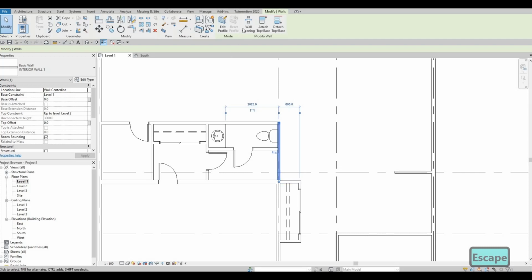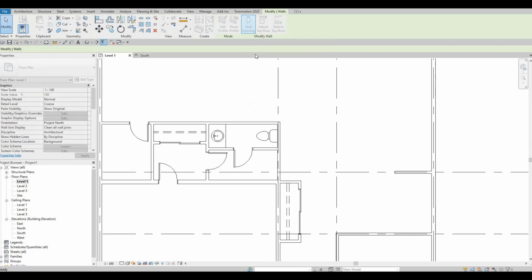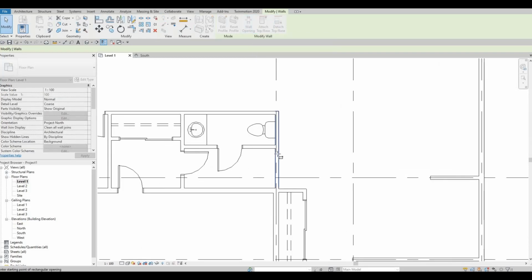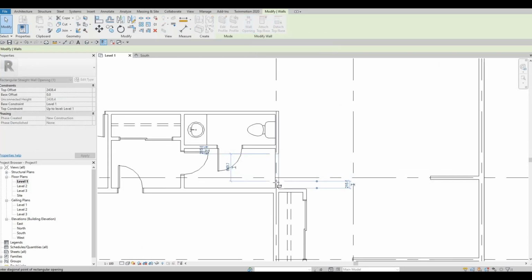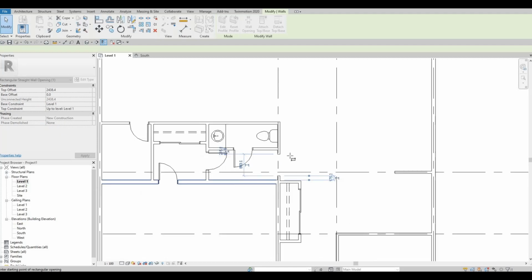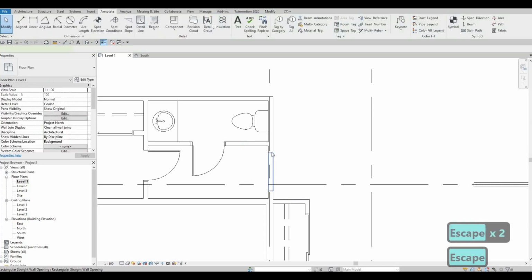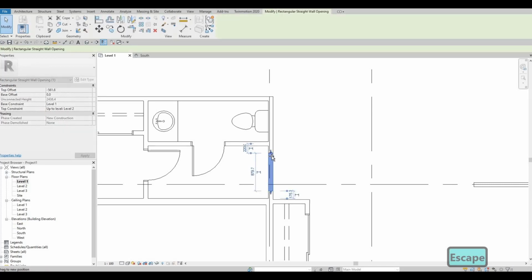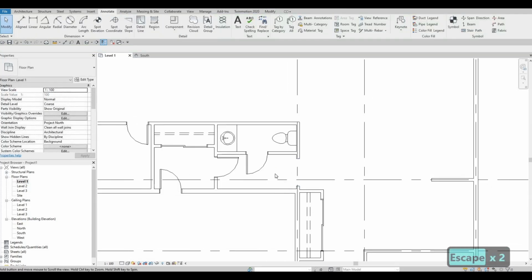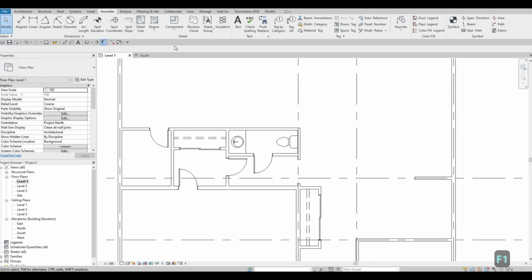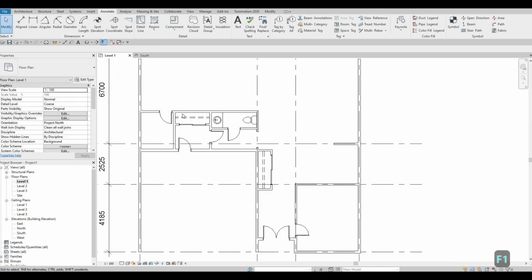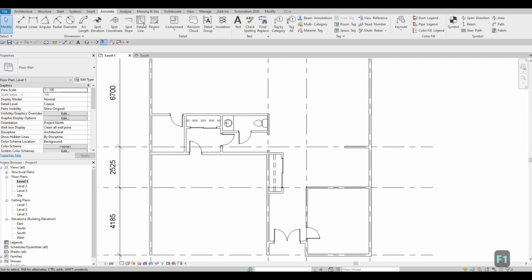We can open this up by clicking on the wall and click wall opening. You just need to click 2 times here, representing the opening. And as you can see, you have the opening now. You can always click it and then adjust the width of the opening. So that's a good way of showing that. And one thing that I want to add again is the pantry.